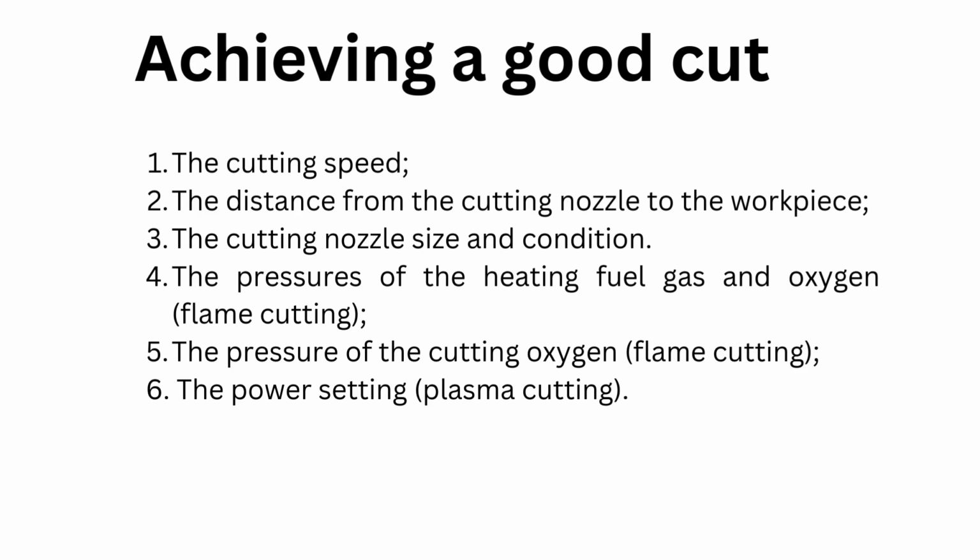1. The cutting speed. 2. The distance from the cutting nozzle to the workpiece. 3. The cutting nozzle size and condition. 4. The pressures of the heating fuel gas and oxygen, flame cutting. 5. The pressure of the cutting oxygen, flame cutting. 6. The power setting, plasma cutting.